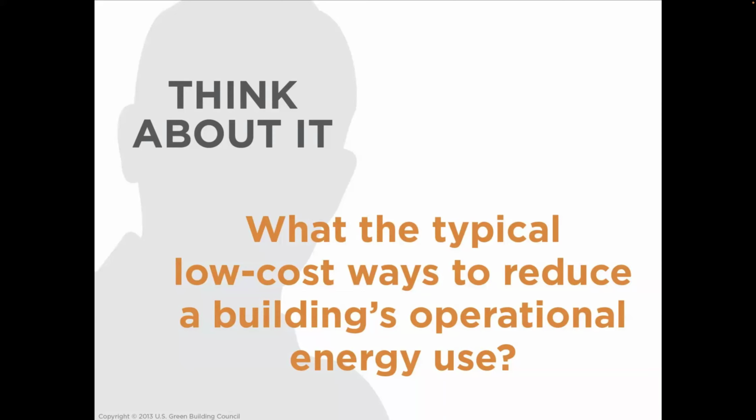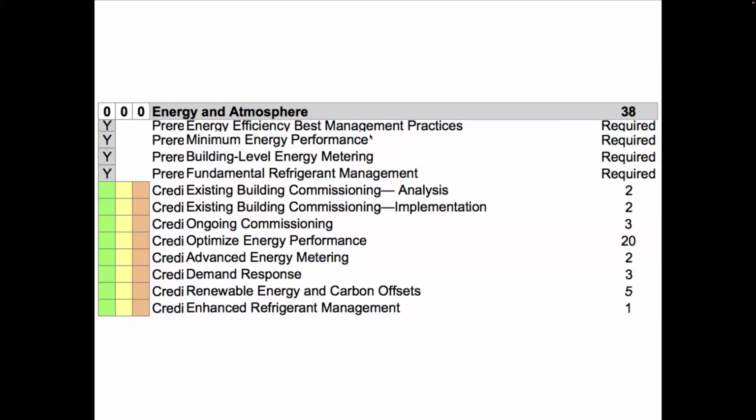And you're going to see everything you talked about in the slides coming forward. All right, so there's a bunch of prerequisites. Again, there's energy efficiency best management practice. A lot of this is policies and also identifying the systems that you have, and schedules and so forth. I'll show you an example of it. It's identifying all the different exhaust fans, HVAC, chillers, package units, itemizing and understanding everything you have that uses energy, and then what the maintenance cycles are, what the set points are, and what the operation plans are.